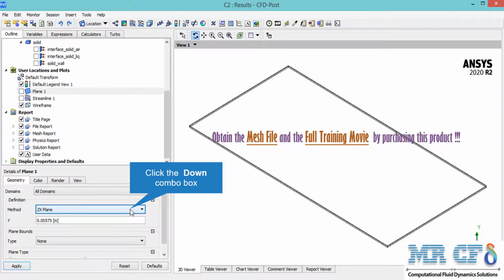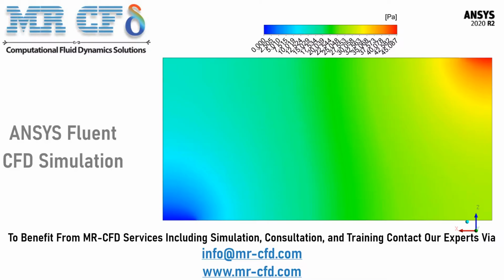After clicking on Location and then selecting Plane, a new window will appear. In the appearing window, under the Definition section in front of the Method, we click on ZX plane and then set the value of y to the defined value. And then we apply to create a new plane. In the shown contour, which is the pressure contour, you can easily see how the pressure of the liquid changes from the inlet section to the outlet.